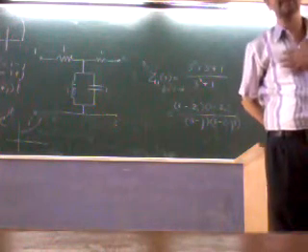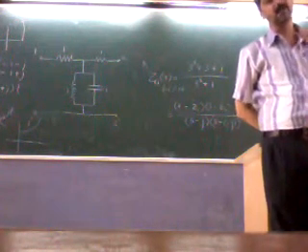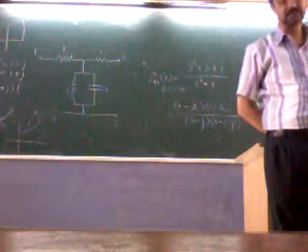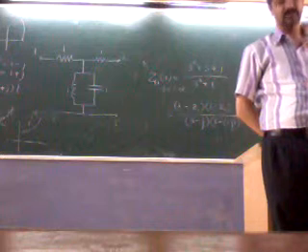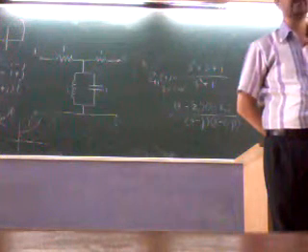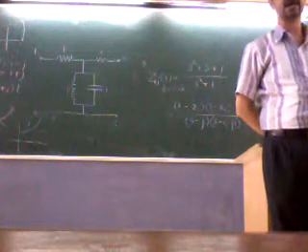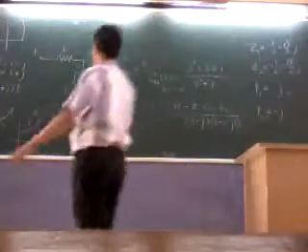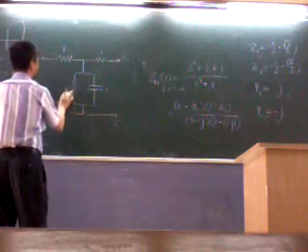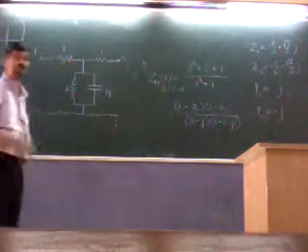And that simplifies my task. The handling of e raised to st is a very easy situation because the integral and derivative operators become scaling operators, and therefore I can replace the impedances by S and 1 upon S, which I could not have otherwise done.